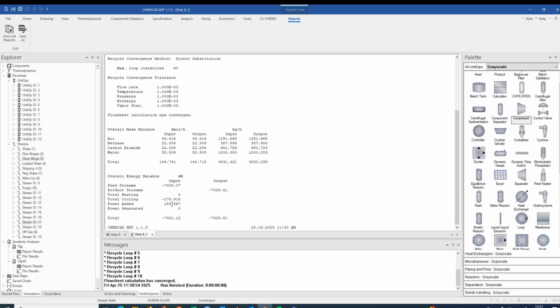And for cooling, we would need cooling machines. So chillers, compression cooling machines commonly are used, and these require again electricity, but not in the whole range of the cooling energy required. So here we will work with the coefficient of performance, the COP value, which will give us the required electricity for a compression cooling machine to provide our cooling energy.